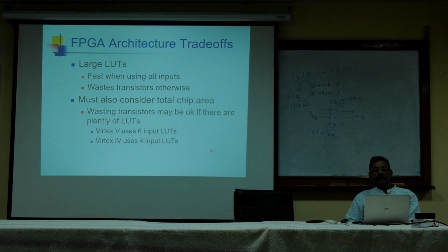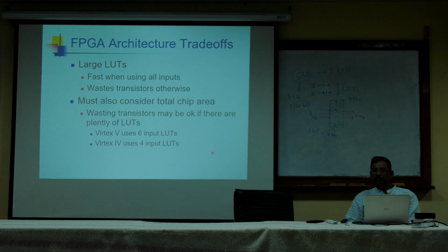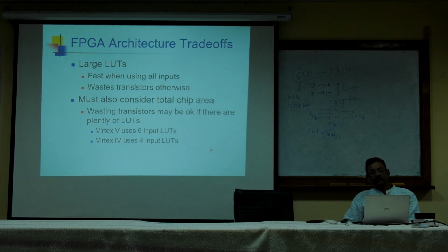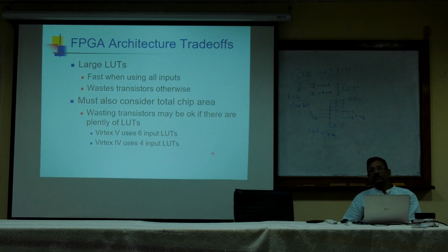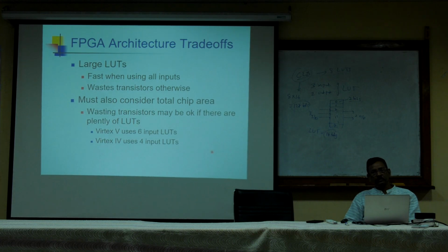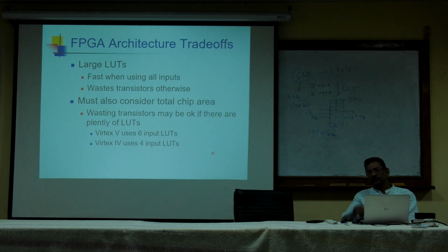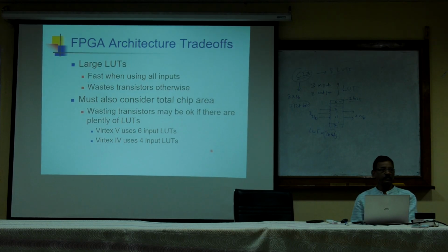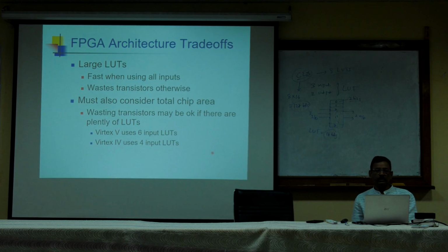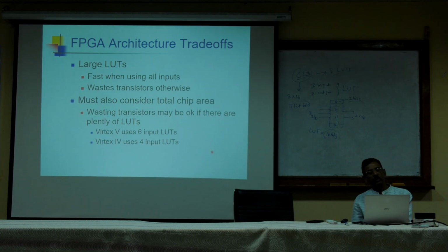Virtex 5, Virtex 6, Virtex 7 also use 6 input LUTs. Kintex, Artix, and all this Zynq FPGA use 6 input LUTs only. Virtex 4 uses 4 input LUTs. Okay, right.